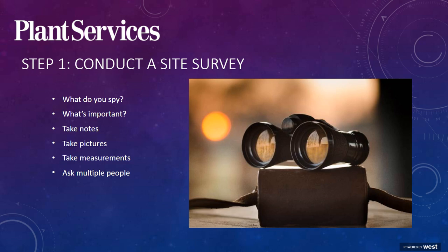Also, consider ancillary support systems during your walkthrough, like ventilation, electrical, and maintenance. These systems will often be overlooked and are more times than not part of the problem and the solution to improve system efficiency and reliability. Lastly, don't forget establishing goals, because you're going to come back to this in the verification step.